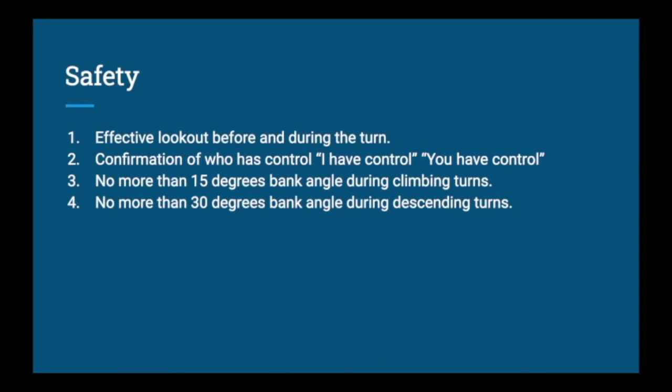Okay, a couple safety items for today. So effective lookouts before and during the turn, just like always. Confirming who's in control using the phraseology, I have control, you have control. No more than 15 degrees angle of bank in a climbing turn. No more than 30 degrees angle of bank in a descending turn.